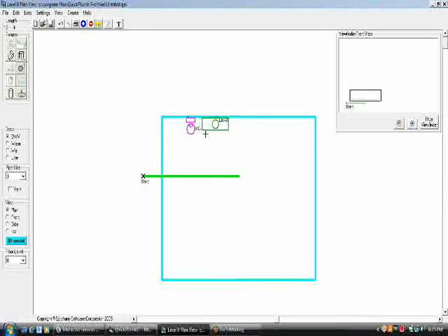And this type of scenario is used where horizontal wet venting is not allowed. This would be considered a vertical wet vent because we're using the vent from the lavatory as a wet vent for the water closet. As you can see, I've already connected my lavatory to the building drain, and so now